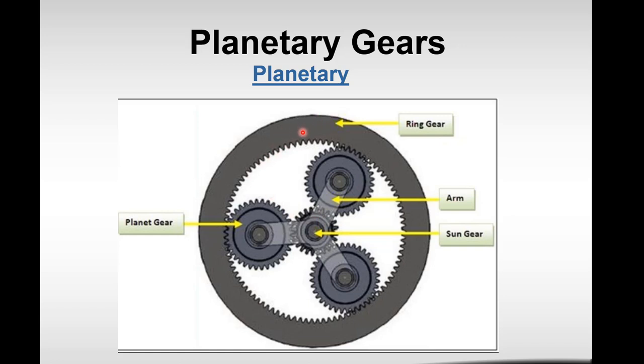Generally with planetary gears, they don't take up a lot of room. They spread out the load on more teeth. It's symmetrical. So there are a lot of advantages to planetary gears, which are basically spur gears arranged in this way. You might, for instance, hold the ring stationary. So now if you drive this center gear, then this carrier will move around.